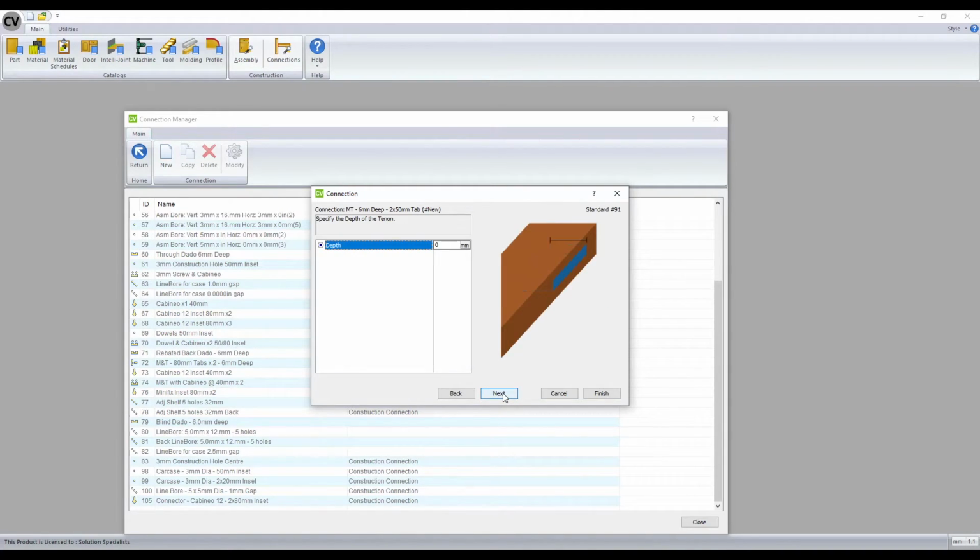The depth of the tenon will be 6mm. The pocket width across the tenon should be the diameter of the downshear tool you plan to use. We will be using an 8mm tool, so I will set this to 8mm.